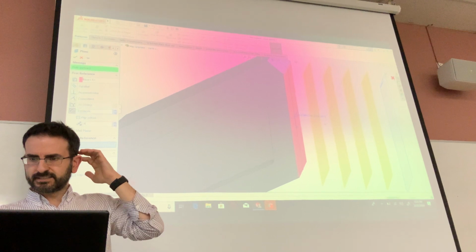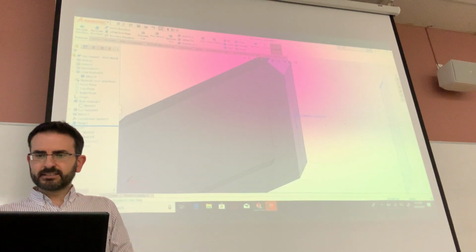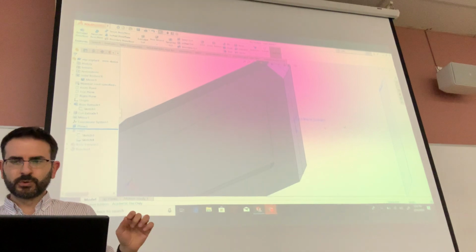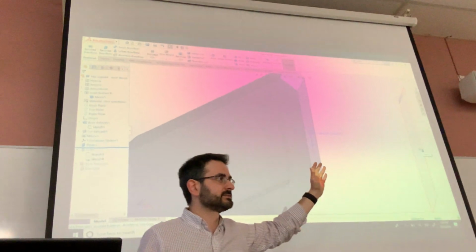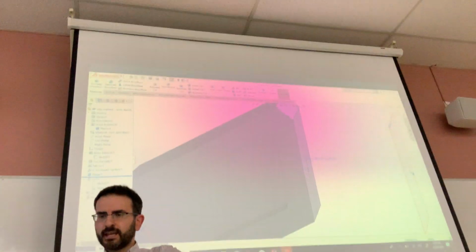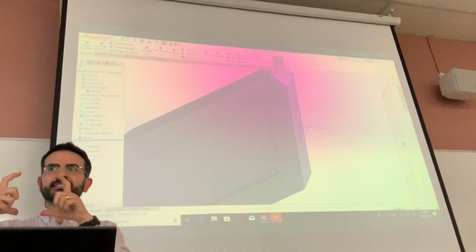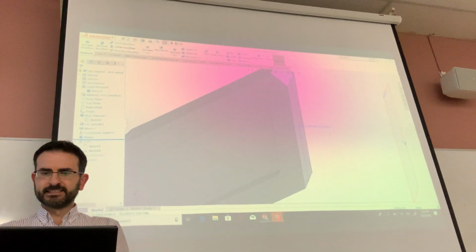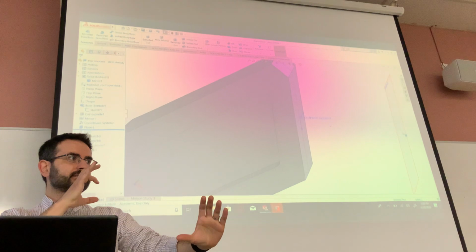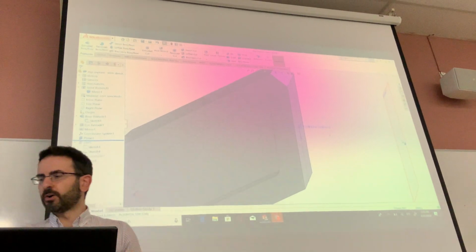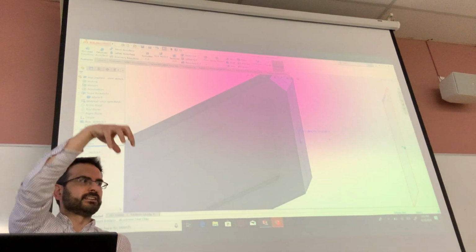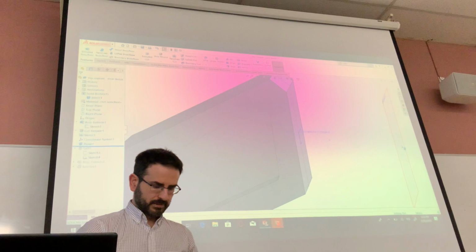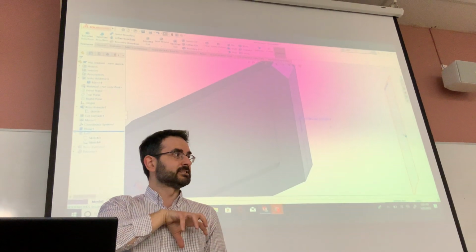I'm not going to create it, because I already have it. Now the part that was also a little bit tricky was that I need to create a circular geometry on this face here, on the 5 face, because I need to loft. And I want to make sure that the circle I create is aligned with the base, so that when I do a loft, it's not a loft that goes skewed. It's a loft that comes up straight, so that if I look from above, the 2 bases are centered with respect to one another. And so, the way,